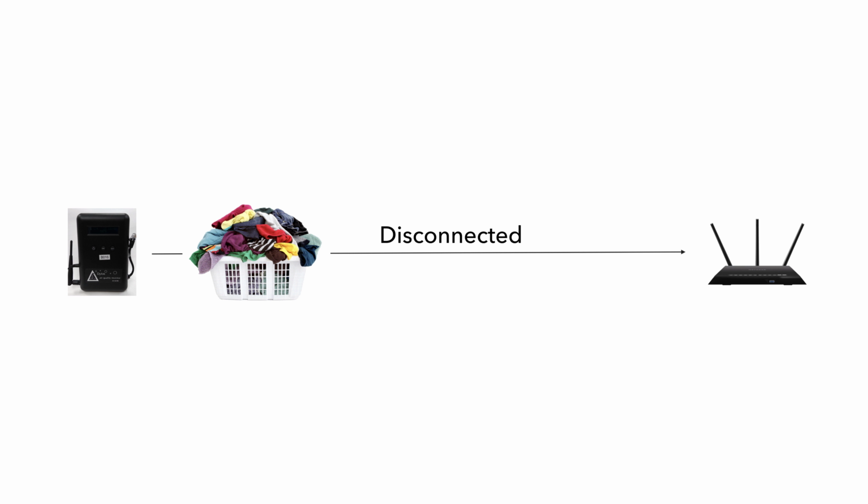This sensor was on the edge of connectivity. The signal to noise ratio was not very great. And so just one little change in the environment, like a laundry basket or someone moving a chair or a door closing or something like that, or furniture being moved, can cause the sensor to disconnect.